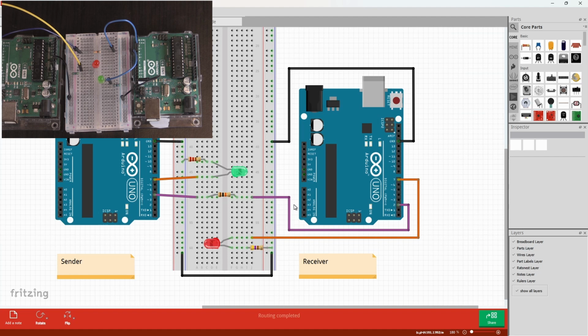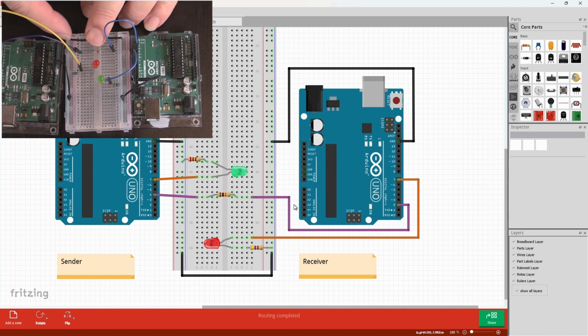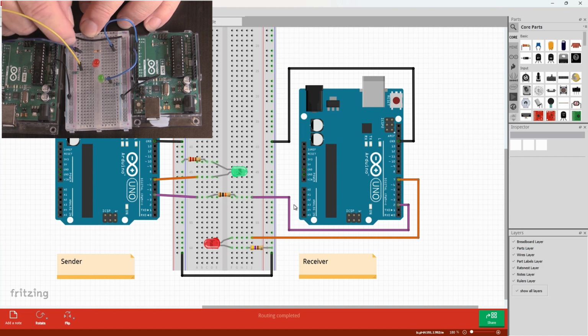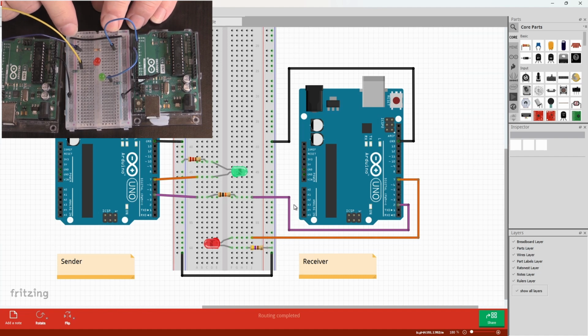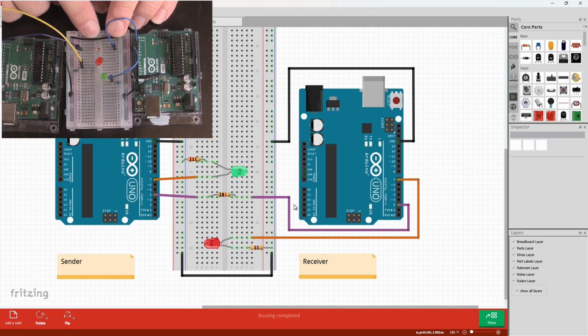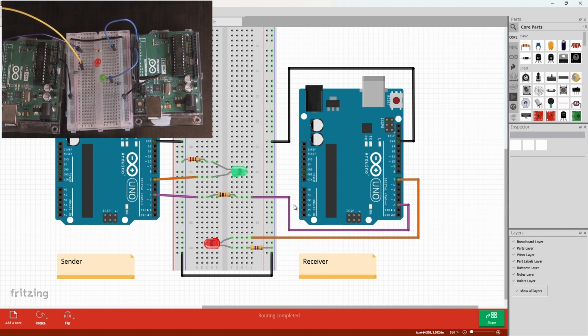To there, so that's our ground, and then we'll use a little bridging wire to connect the two sides up. So it's important to have a common ground reference, because that's how the two systems can measure the signal. So when this is 0 volts, then obviously the signal will be equal to the ground, but when it's +5 or high, then there's a relative difference between the ground and the signal on this communication, so that's how it detects the high.